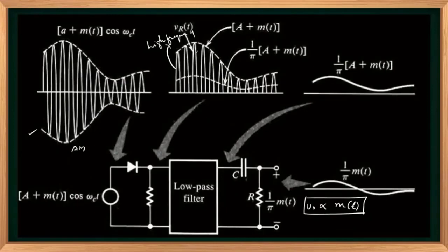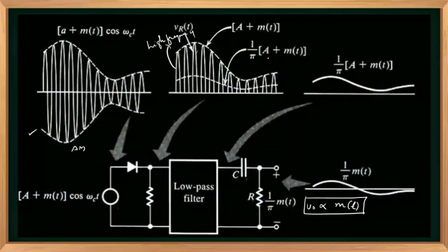There is no doubt about that. So here, these pulses contain higher frequency components and higher power. But the amplitude variation of the signal contains low frequency components and less power compared with these pulses. So when we suppress the high frequency component pulses, the demodulated amplitude level will also be less. It will contain a DC component as well as the modulating signal component.